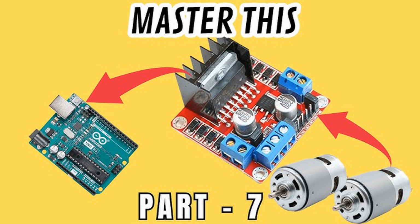Operation: MOSFETs, metal oxide semiconductor field effect transistors, are used as switches that can control large currents with minimal heat loss, making them efficient for high-power applications. Applications: Common in high-power applications, such as electric vehicles, large industrial machinery, and robotics. Examples: High-power MOSFETs are often used along with microcontrollers or dedicated motor driver ICs to provide PWM control.